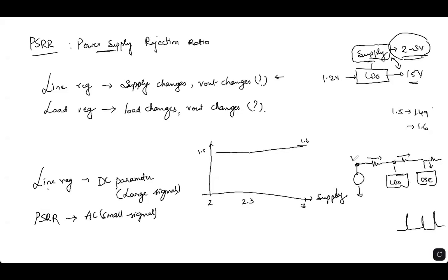The voltage which was here, let's say 1.5 volts, it could be an LDO, or let's say 2 to 3, right? Okay, let's say this is a battery where it is supposed to be 2 to 3 volts, so anywhere in between. Let's say it is at the minimum, 2 volts. What happens if there is a huge current taken in this path? This path, we'll see, it was 2. The moment there is a current being taken from the oscillator, this drops. There'll be a drop. It could go up to 1.9, 1.8, whatever it is.